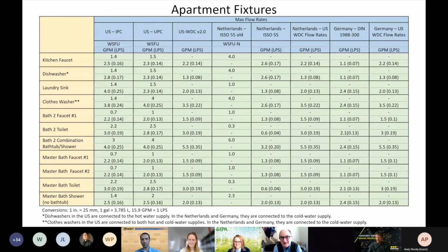And so we're starting out at a deficit to begin with, based on the way we rate the performance of things. Anyway, for example, here the standard value for the supply for the mains pressure from the street is up to 5 bar, and then you get a figure of a required available pressure at a toilet cistern of half a bar. So you can waste 4.5 bar on filter, water meter, and everything else in the system until you reach the fixture. Right.